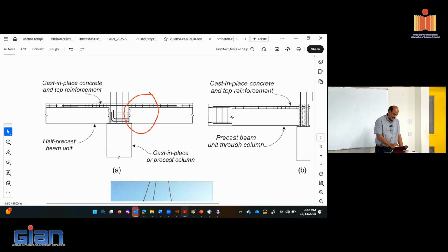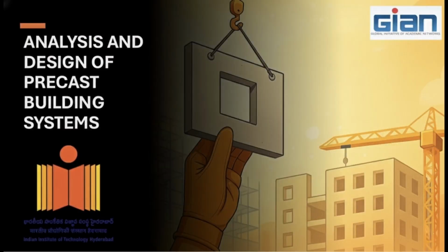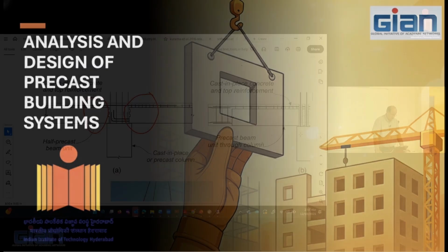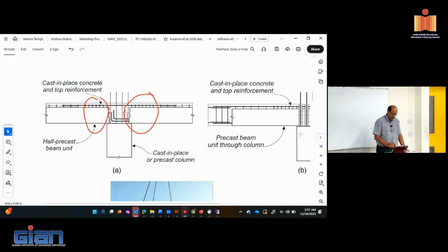So the typical non-seismic details, when transported to seismic application, that's something people paid attention to. The region doesn't get strengthened, so that if you strengthen this region, then the plastification will start to take place outside of where you think it's going to, or you envision it's going to take place, and that initiates other problems as well. We briefly talked about that.